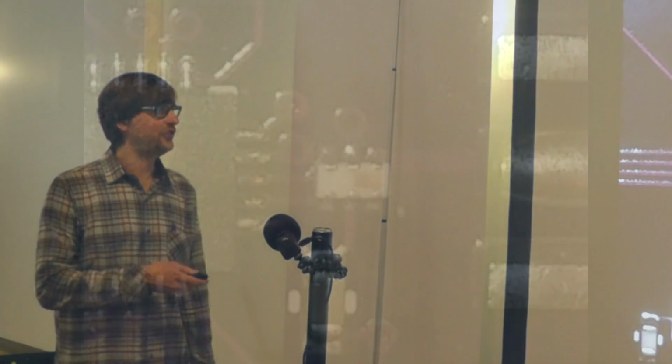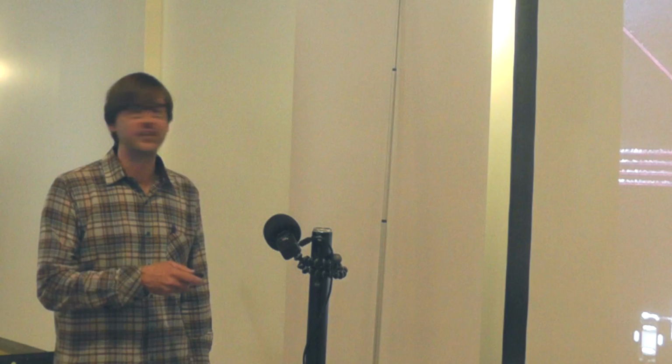I Googled NRF24L01 Plus balun, and I found two manufacturers that just sell a single component designed specifically to match the differential impedance of this chip and convert it to 50 ohms. It costs something like 20 cents. Instead of a mess of capacitors and inductors, it's kind of a no-brainer to use this thing.